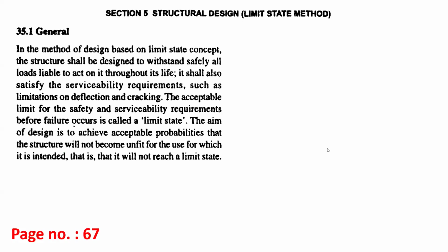So we cannot go in detail in the class. So now you can go very clearly with this. So now you can see what is limit state. They have mentioned in the method of design based on limit state concept, the structure shall be designed to withstand all loads liable to act on it throughout its life. It shall also satisfy the serviceability requirements. Means loads, generally we are considering collapse loads. And therefore that limit state is known as limit state of collapse.